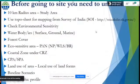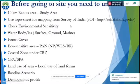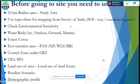You can just go, and before going to the site, you need to understand the area, that is the study area. So study area with reference to your project, 10 kilometer study area is required nowadays. Then you have to use a topo sheet that should be procured from Survey of India. You can have the link, it is already provided. Then you can download a topo sheet from that, and then you can process. This is available freely, but it is not for commercial use. But if you are going for commercial use, then you can procure the topo sheet from Survey of India. It has a very reasonable cost, starting from 70 rupees only. So you can easily procure it in soft copy and hard copy as well.